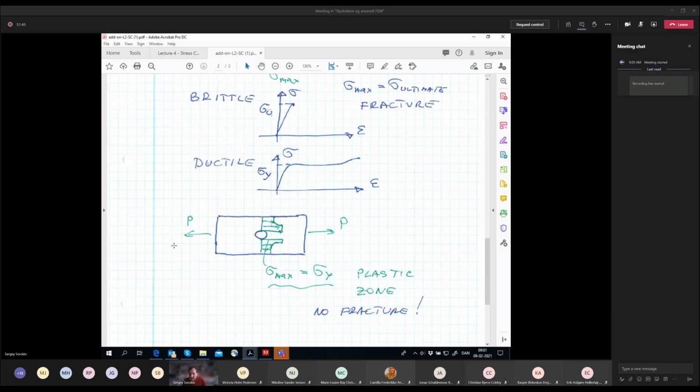It's a change of the structure. Change in radius, change in width, that's a change in the structure. The change in material is whether you take high quality steel with yield stress 700 megapascal, or mild steel, which is way cheaper, with yield stress 350 megapascal. Okay, I was just a bit confused then.